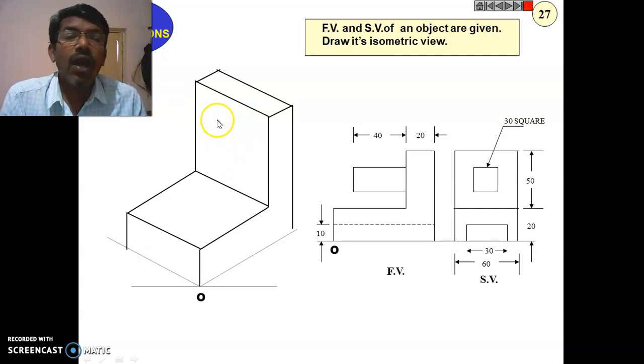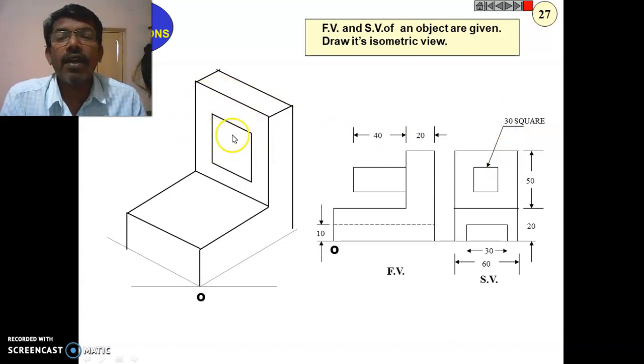So now I will form a square centrally onto this one, on this 50 mm plate. Okay, so now I will construct a square by taking equal sides, that is 30 mm. Already this is 50 mm, right? Okay, this is 60. So I will take 30 mm means this side 15, this side 15. I will leave it out. First of all, I will make the center points. Then next, I will extend.